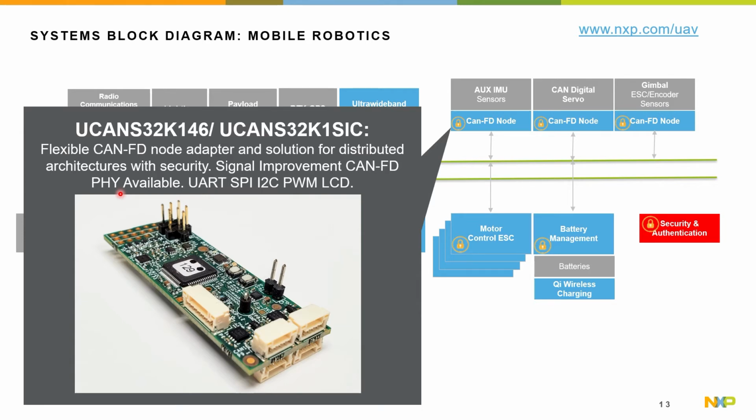So if you hooked a GPS and an IMU onto this, it could actually calculate, let's say, an EKF and provide that back into the system. The flight controller would just see it as another set of DDS services, a publish-subscribe type event.